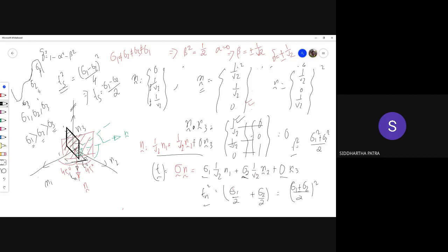Now, the direction of maximum shear, or the maximum shear stress, only makes sense once you talk about the shear stress value on a given plane perpendicular to one of the principal directions. That means on one of the principal planes. So we can talk of maximum shear on one of the principal planes.